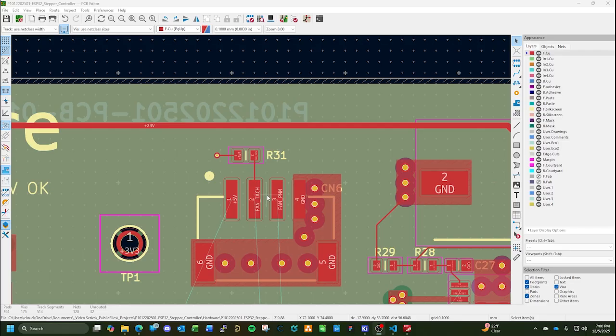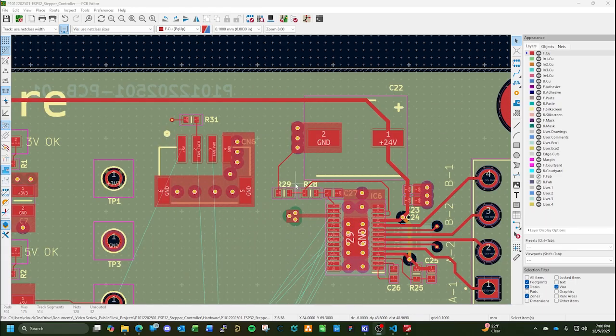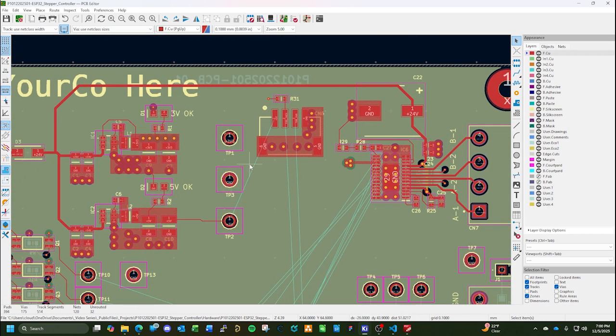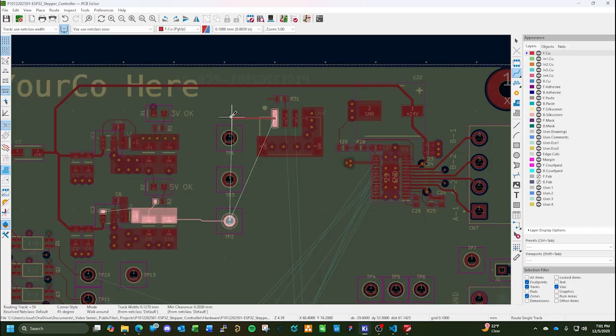I've already got a library written for the ESP32 for a PWM-controlled fan with a tach. You can control its speed and read the tach and everything from it. So I've already got one written that will just drop in for the ESP32. So now I have the 5 volt, which works out perfectly because we can sneak up and all around there with a nice big heavy trace. So let's come off of this guy.